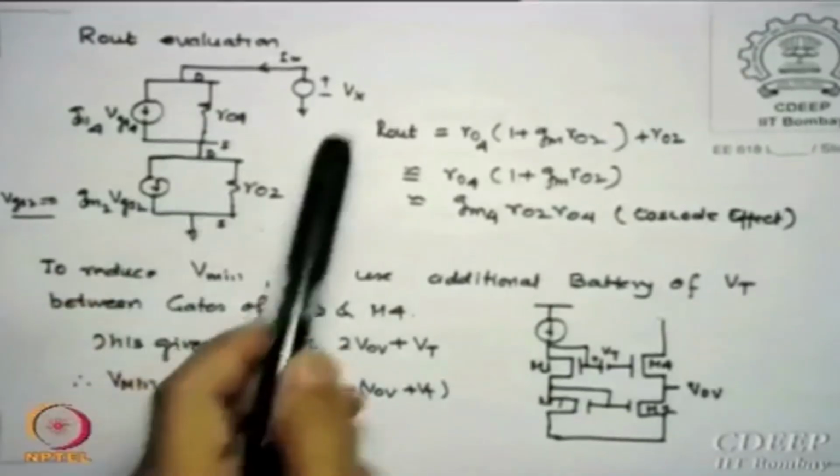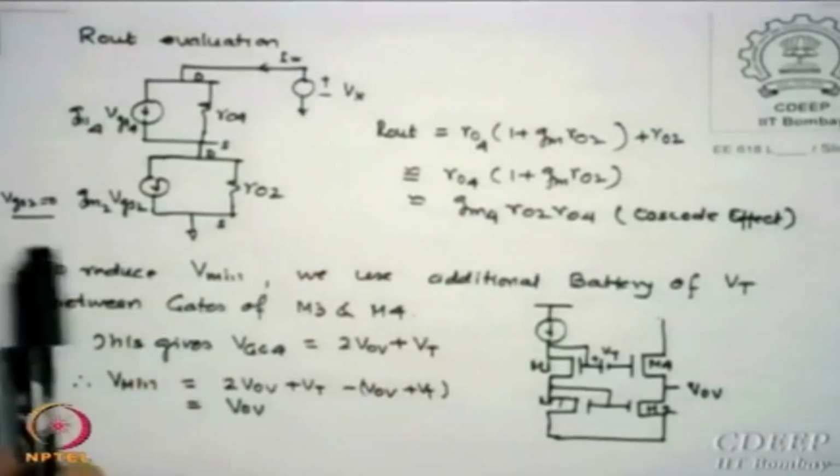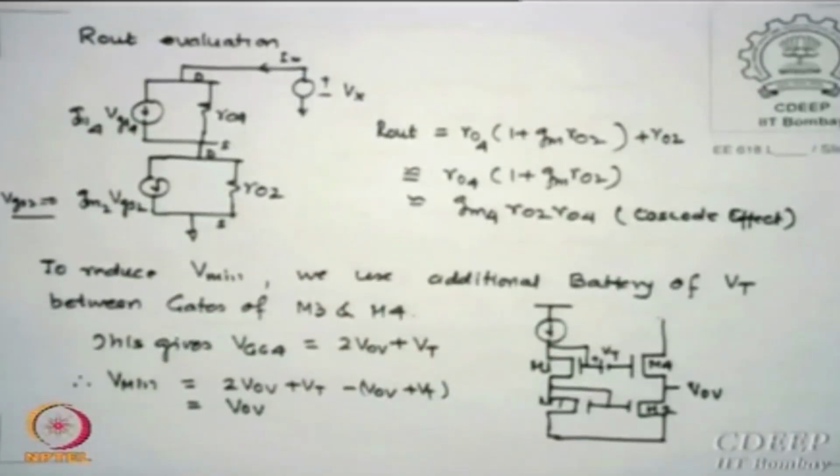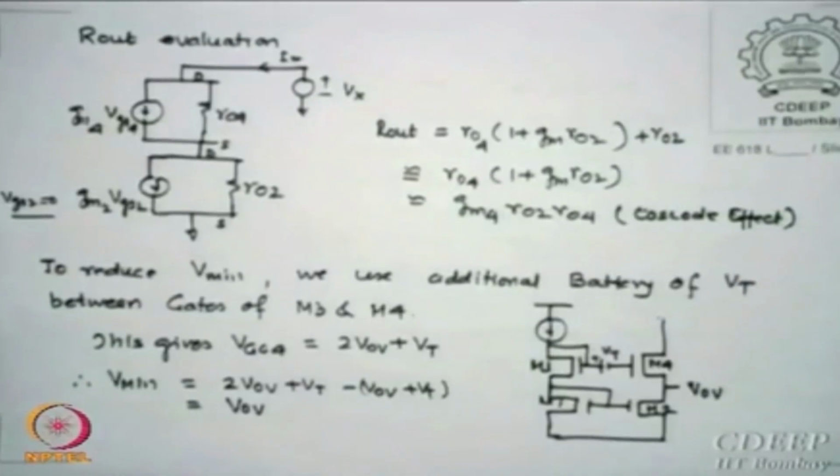So these are equivalent circuits. I apply a Vx source, pass an Ix current. Why is VGS2 0, I said? Because the source is coming from reference, and that I must actually create it to 0, no current in the reference. All current sources are opened and voltage sources are shorted. So the other side of the circuit is not necessary because there I am forcing VGS2 to go to 0.